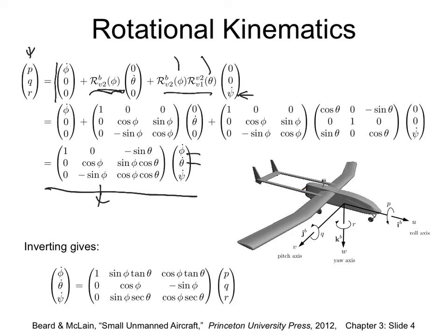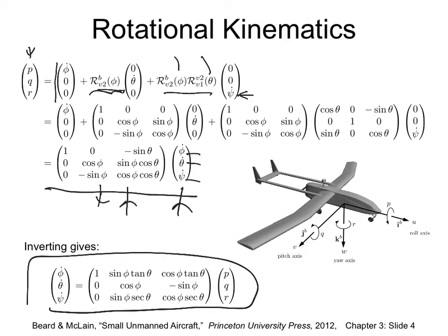So now we have phi dot, theta dot, psi dot equals to PQR, but we are solving for this, right? And so just take a transpose of this, and we can write this equation here. Right? No need of inversion, just transpose is sufficient. No, I think there's a confusion here. So yeah, I will take my words back. I think that this is not a rotation matrix in that sense, because this is not a transpose. You actually have to invert that matrix. That's why you get this tan theta, sec theta. So this matrix is not the rotation matrix, but when you take the inverse of this matrix, you can compute phi dot, theta dot, psi dot.